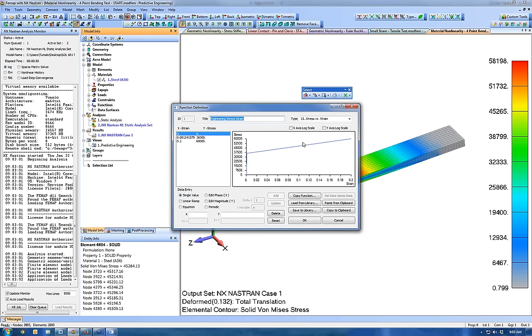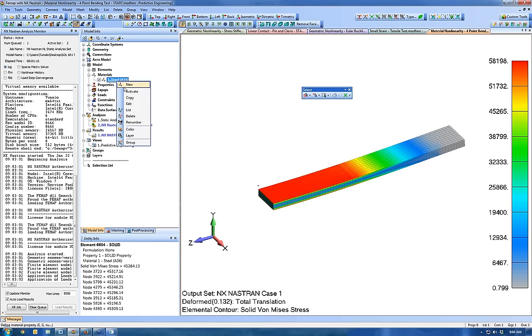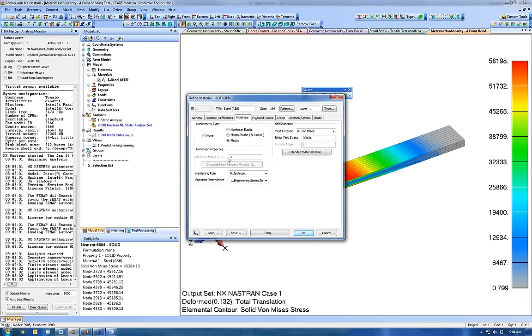So what we want is the slope of this curve here. And our strain at yield is very small. I'd say it's negligible. So all I need is the rise, which is the difference between yield and ultimate, over the run, which is the difference in strain. And that'll give me the slope of that curve. So let's come in, edit. We're switching here. So again, rise over run. Rise would be 60 KSI minus 36 KSI over the run, which is 20% strain.